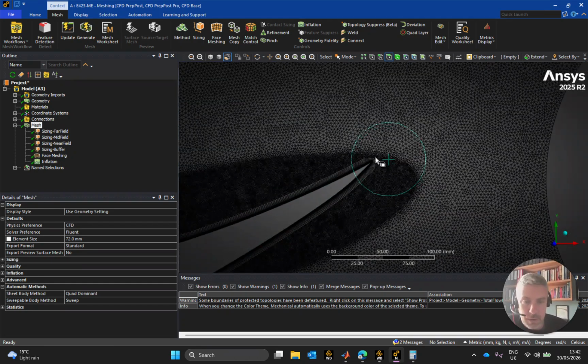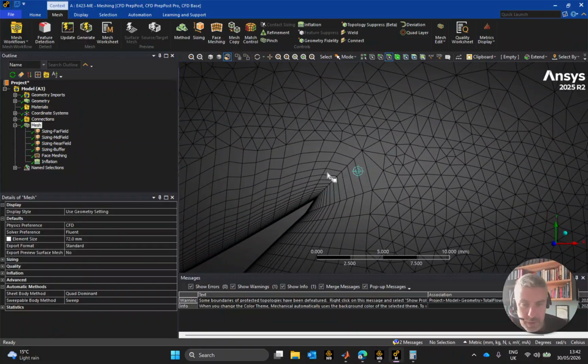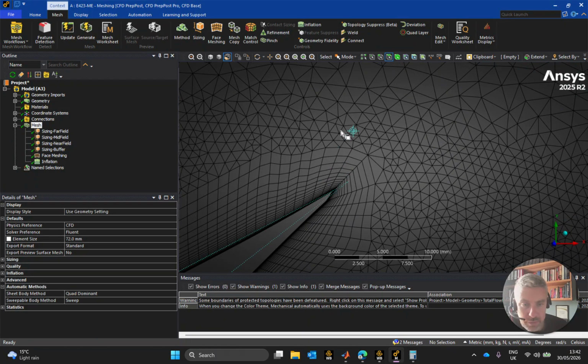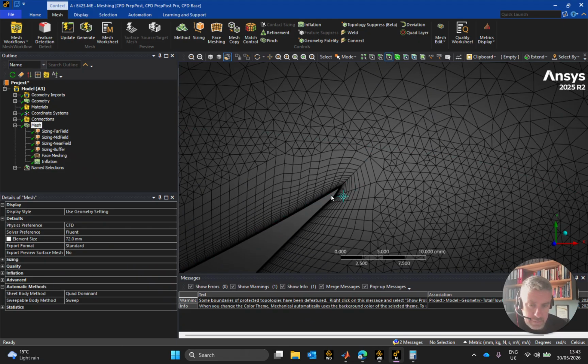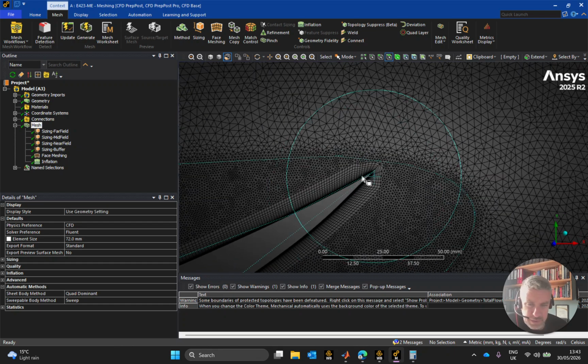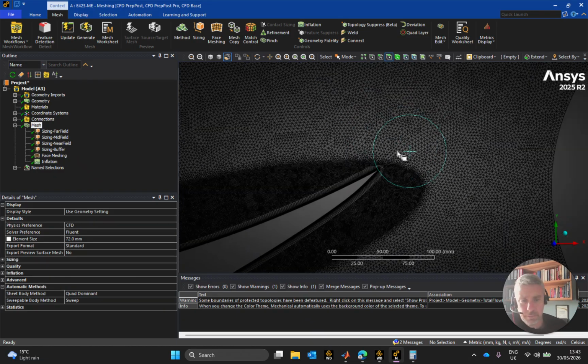Now, this is where I want to check. So there's our boundary layer. Right. Now, we have a couple of nice little tight enough 1mm buffer mesh elements, cells there between the top of the inflation layer and our midfield region, which is grand. Have a wee bit of scope to move, and I'm at the maximum angle of attack that I'm going to run this main element at, 15 degrees. I'm not going to pull it up anymore. I'm more likely to drop it down, and if I need more angle of attack, that's what I'm going to rely on the flaps for.